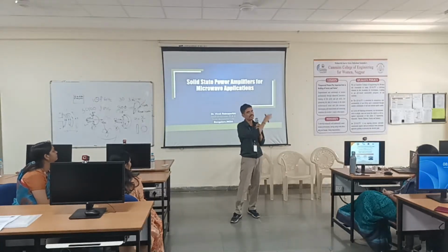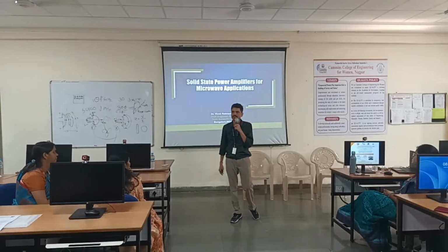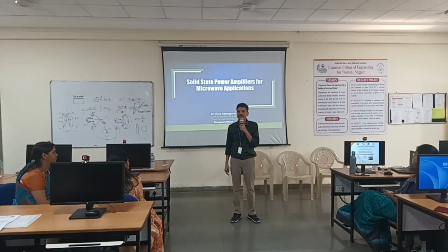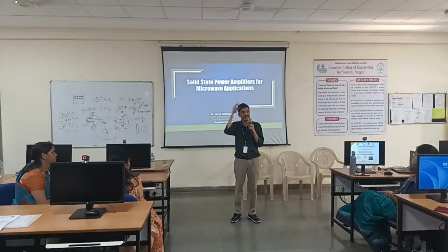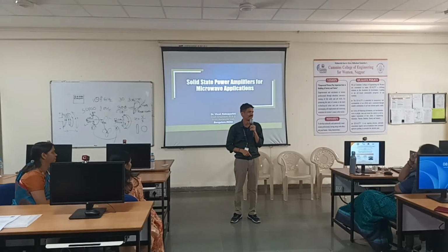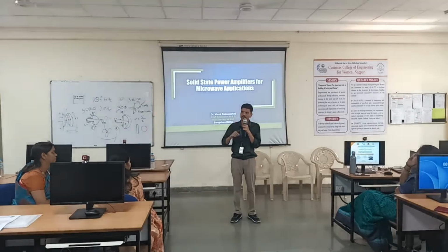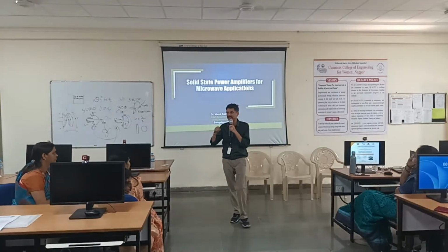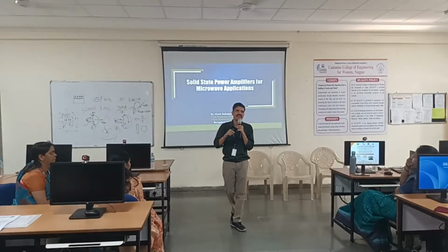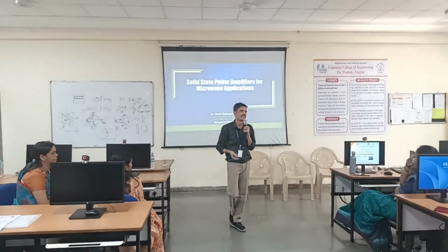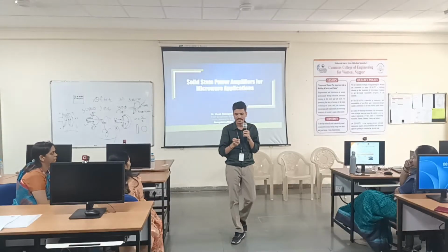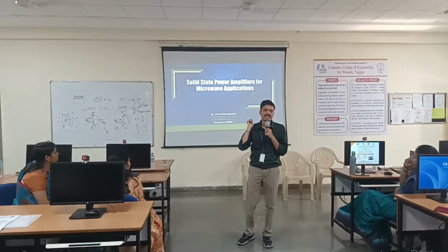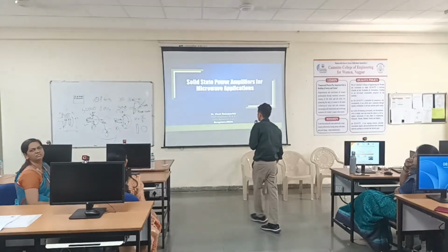Similarly, if you have a radio, something like what we do for BTS towers, your PA itself occupies more than 60% of the space of your entire radio, and it consumes more than 40% of the power of your entire radio. So the most power hungry and space hungry block is the PA. There we can't go with TWTAs, so we have to go with solid state, something designed with transistors.